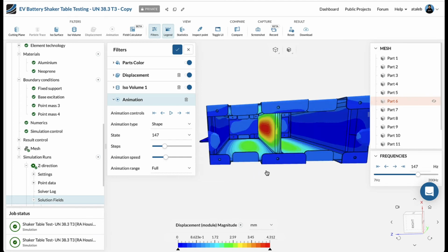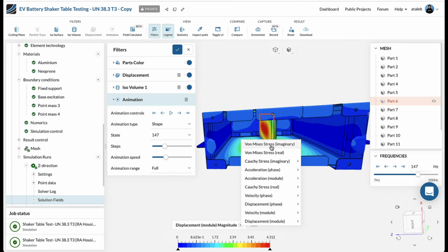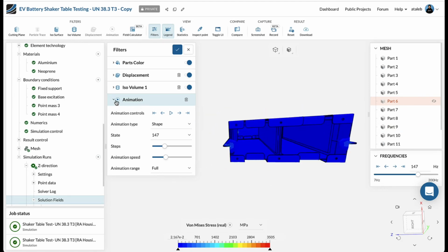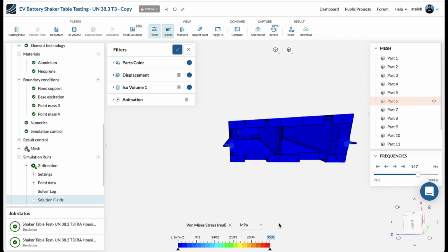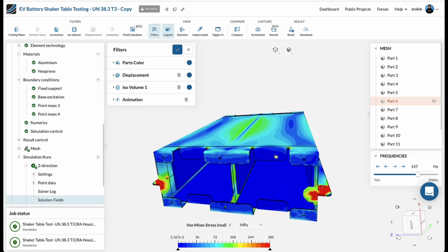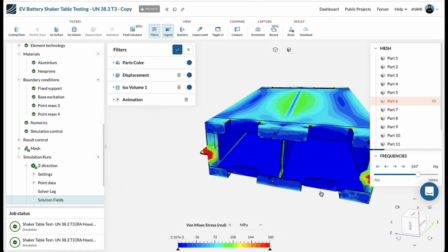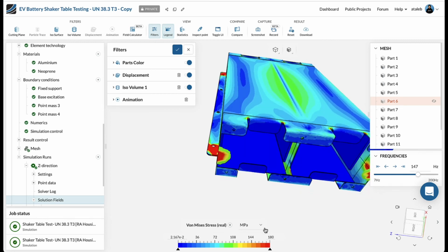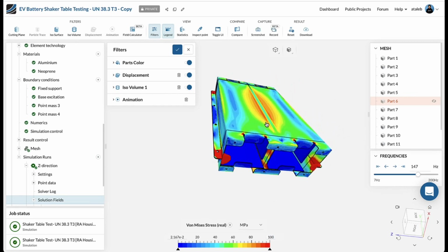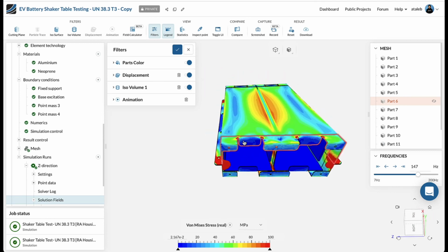Next up, let's have a look at the stresses. We'll find maybe here a stress of 180, for example. So we are seeing here that we have pretty high stresses in extended regions. Actually, it seems to go beyond even the 180 megapascal. Or if we keep this at 100, let's say, we see that actually we exceed the yield stress in many